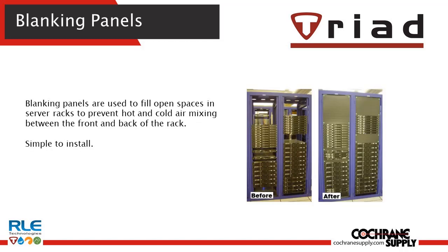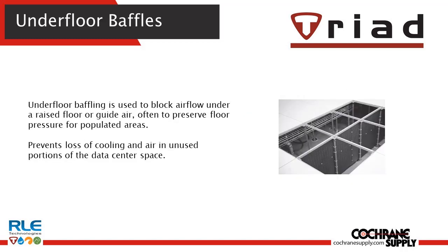Another area where we can help our customers is with blanking panels. We've talked a lot about airflow and how it flows through the server inlets in the data cabinet. If you're mixing the hot air and the cold air and not parsing that out, you're really ineffectively cooling that space. So putting blanking panels in your data cabinets is something we generally would recommend.